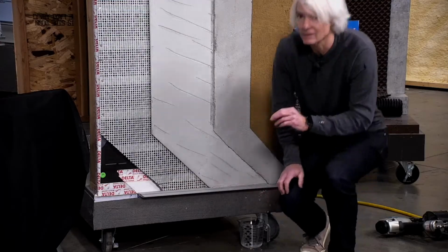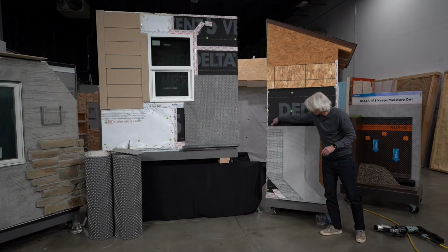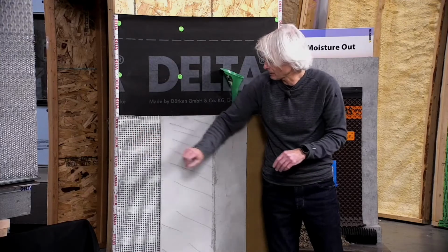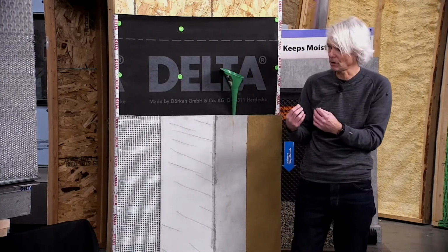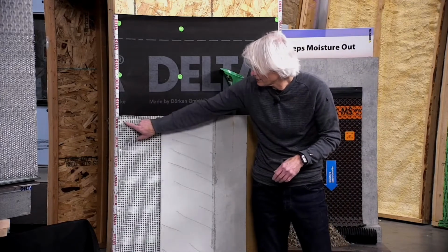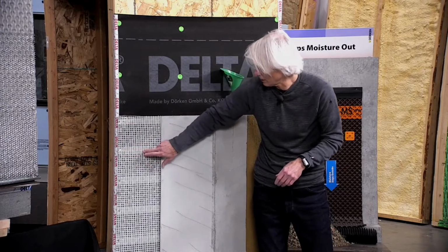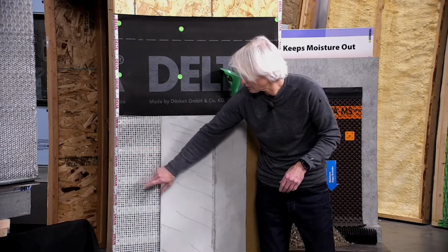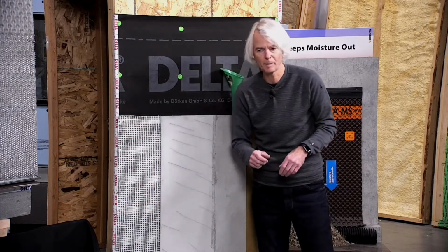So the next piece here is a different product with the same dimpled membrane. It comes with a wash-treated fiberglass lath on it, so not a metal lath. So this one's even faster to install because I don't have to deal with a lath. It's integrated into the roll. Nice thing is you can see it's got a wash-treated lath, and you can see where it's doubled up here. There's more of the fiberglass material. That shows my basic 6-inch nail spacing increment.